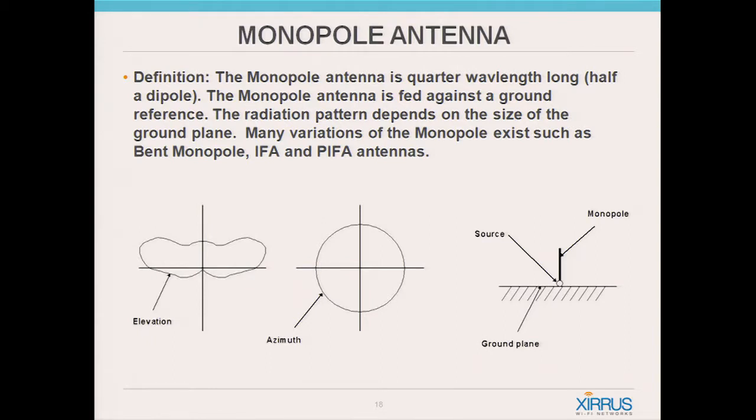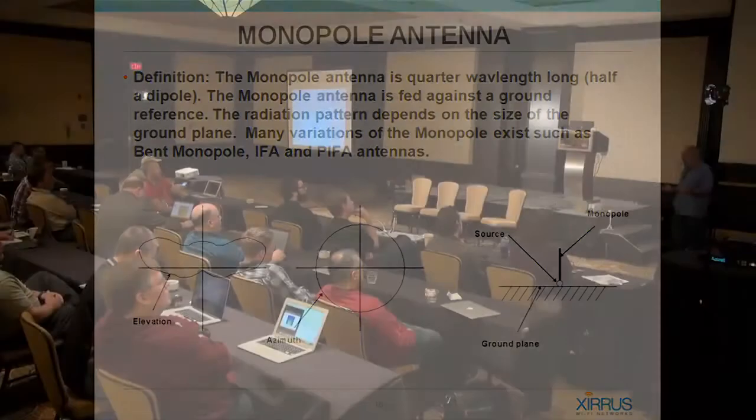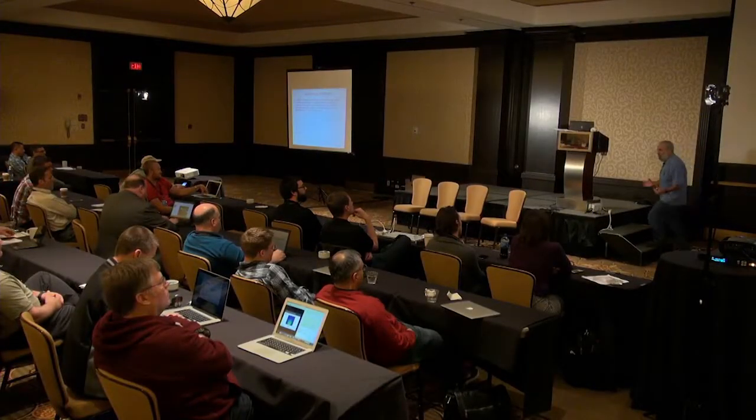The problem is that as you make the antenna very low profile, which is nice because it fits physically into your design, you start to shrink the antenna bandwidth, and you start to suffer from lower efficiency. The antenna is not as efficient. So if you try to transmit a certain power, a lot of the energy is going to be reflected or is not going to be transmitted. So it becomes an ineffective radiator, but in some situations you don't have a choice because size constraints are the driving force.